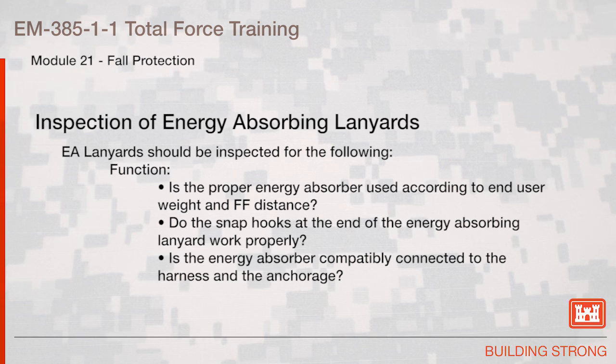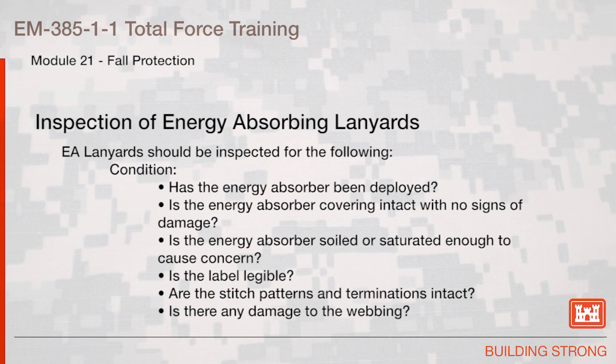Do the snap hooks at the end of the energy absorbing lanyard work properly? Is the energy absorber compatibly connected to the harness and the anchorage? Condition: has the energy absorber been deployed? Is the energy absorber covering intact with no signs of damage?